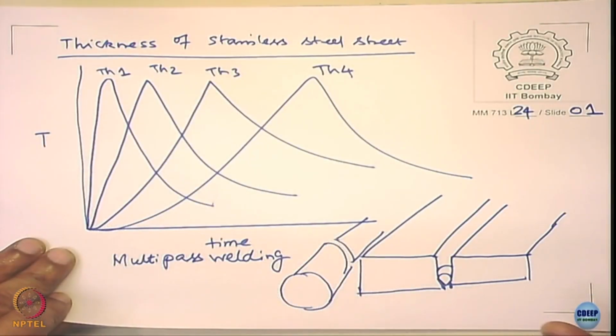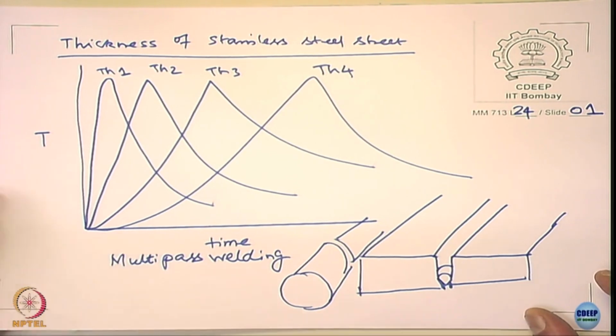So there are various ways people weld. In aerospace industries also, they normally cool it using copper blocks. You can put a copper block and then start welding. The copper block extracts the heat. There are several ways of lowering the quantity of heat and then increasing the cooling rate so that you can avoid sensitization of weldments.